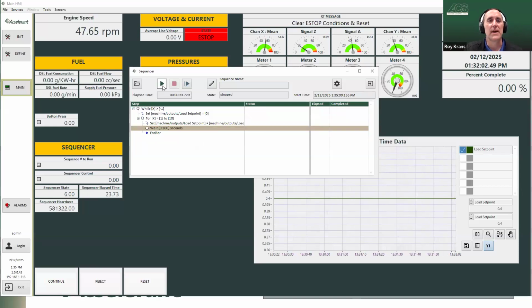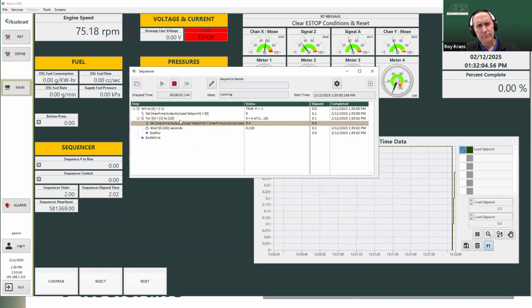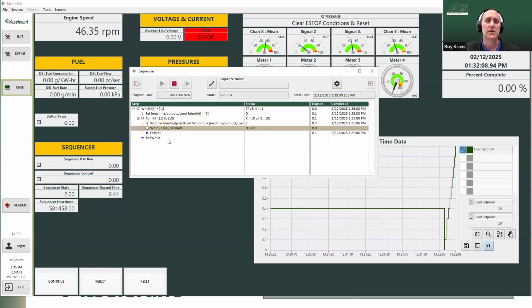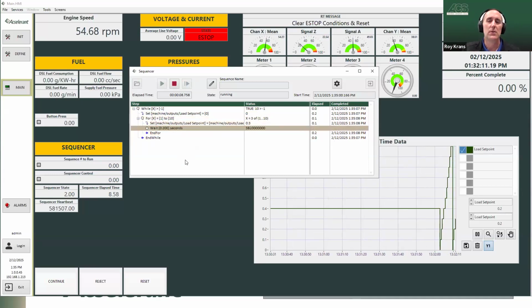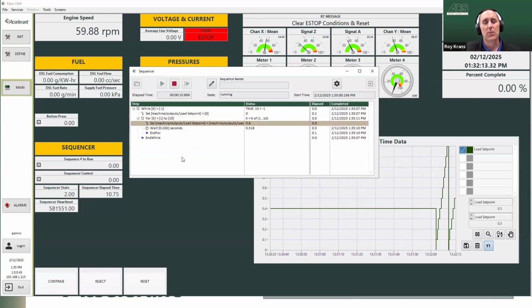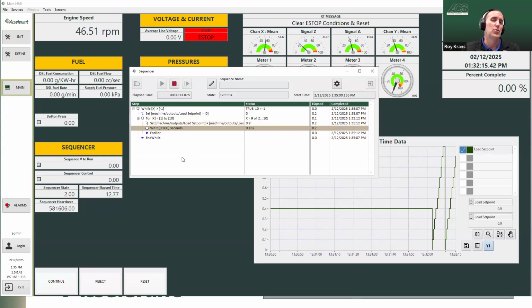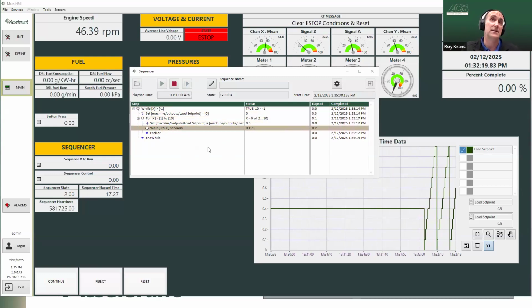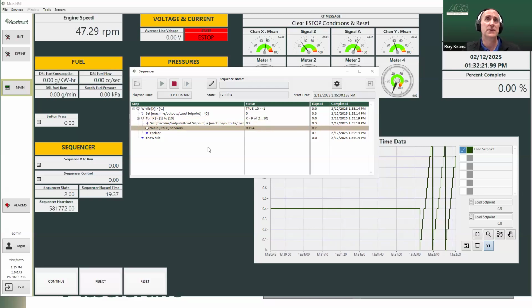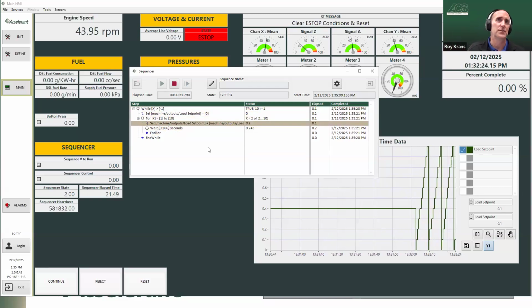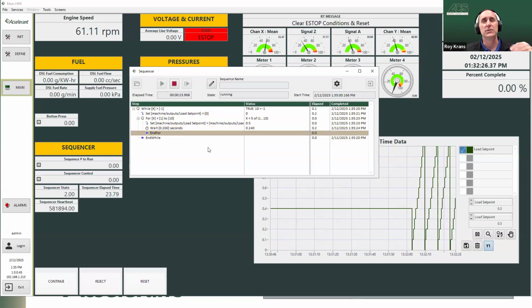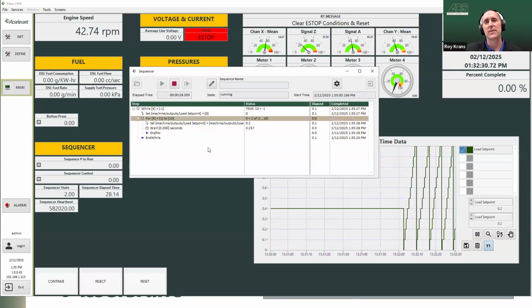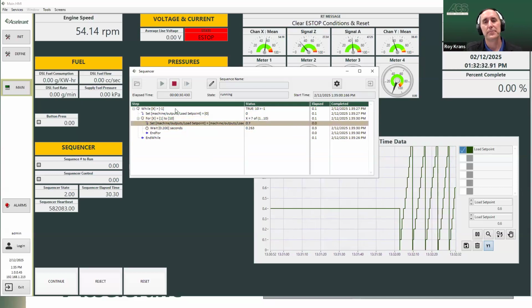So if I execute this one, it's just doing a perpetual loop of modifying a set point a little bit over time and then going back to zero. Somewhat non-deterministic because I'm not telling the real-time side to do this. I'm just doing it on the Windows side. But in many cases, that's sufficient. You don't need the tight real-time control. You let the real-time controller do it. And on Windows, you're just doing sort of high-level, hey, just turn this on, turn that off kind of control.